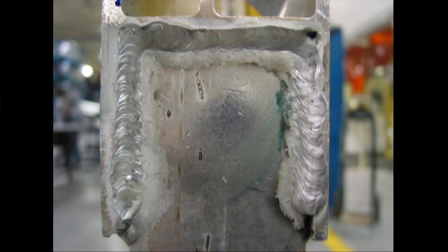Here's a weld that was completed. It was done by the robot. There's nothing from a specification point of view that's wrong with it. I don't like the end of this. Now, notice that this is done in one pass. I've had this happen where people have started to see this area here and they've started to fix it because it's not a complete weld.